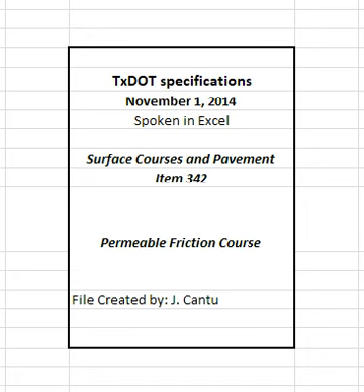5.1.2 Measured percentage. The averaged measured asphalt percentage from each sublot will be used for payment for that lot's production when the measured percentage for any sublot is more than 0.3 percentage points below the JMF target asphalt percentage or less than the minimum percentage specified in Table 4.